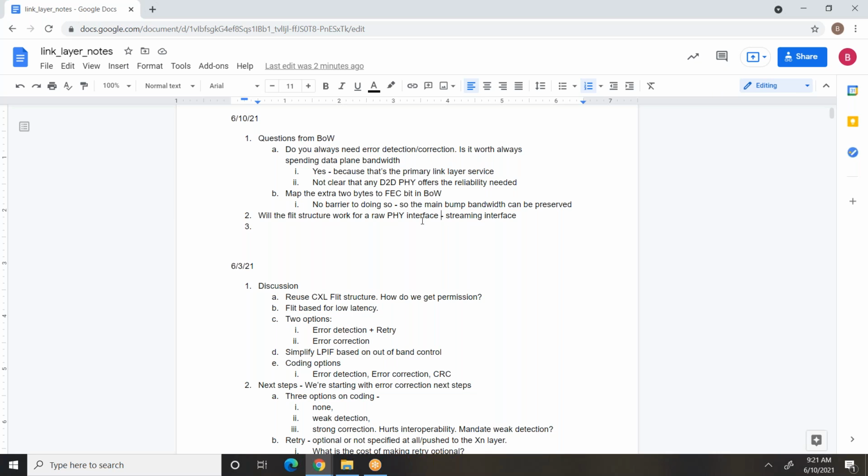You're just replacing the wires on the board with another medium, and you're trying to map the 16 PCI lanes onto 64 wires, low speed wires, or say 64 wires where each wire, it's kind of a reverse bow mapping. So as far as the PCI PHY is concerned, it's actually talking on a PCB trace, but in reality, the PCB trace has been replaced by a multi-lane cable.